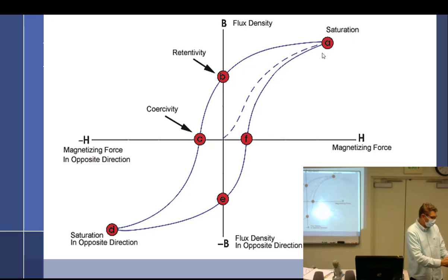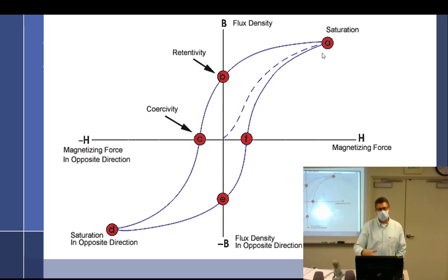Okay, so if we were to lay the crankshaft down, we'd bring up that Gauss meter and go, whoa, it's swinging real hard to the positive, right? But then we go to the very next crankshaft, do the same thing, and that one's going negative. One's got magnetism going one way and the other's going the other way. So one's got a north at the head and the other one's got south at the head. Understand? What I'm trying to say here, not eloquently, is that you have flux density going one way versus the other, and that's like the plus on the Gauss meter, and this is the negative on the Gauss meter.